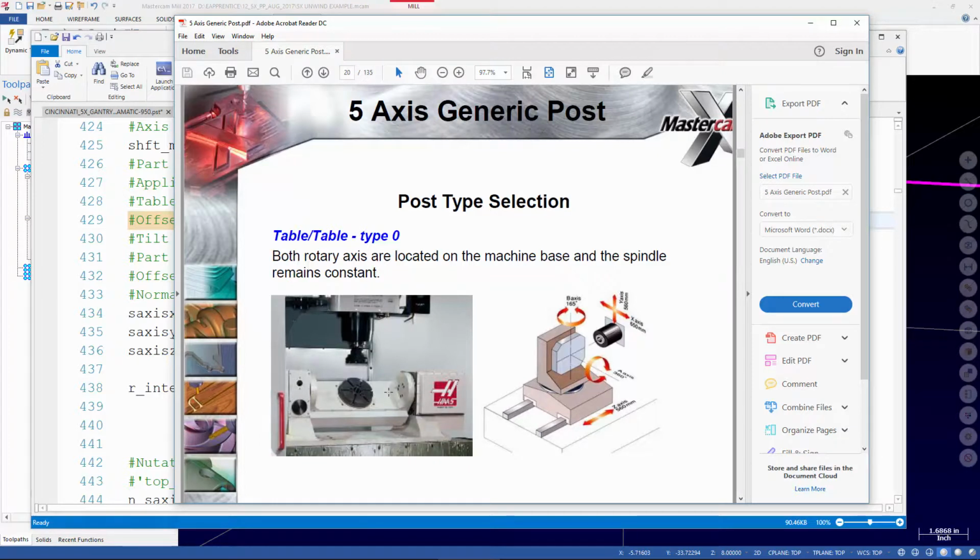When we're looking at it, we have this A-axis center line for the machine. Now, they happen to label their platter a B-axis. Forgive them, Lord, they know not what they do. Okay, so there is typically about 125 thousandths of an inch shift between the center line of the A-axis and the height of this platter on the machine.